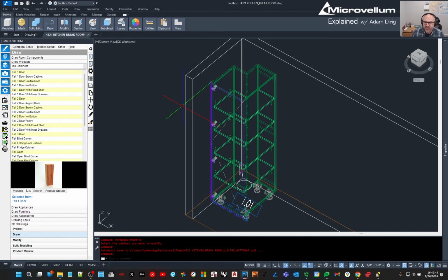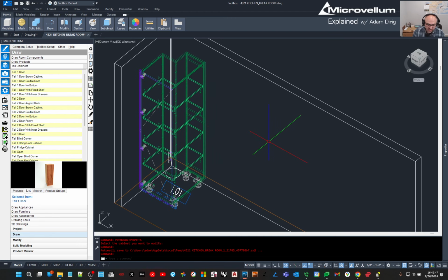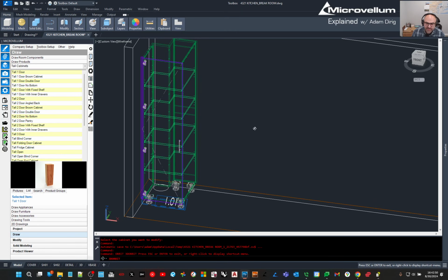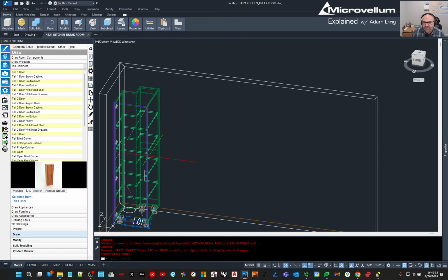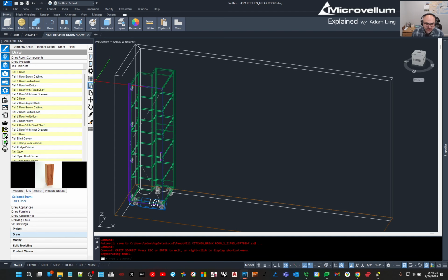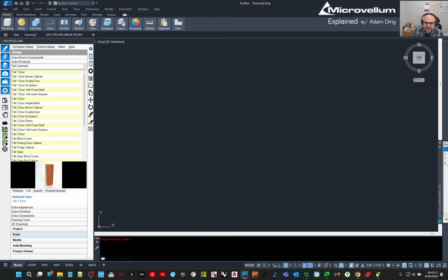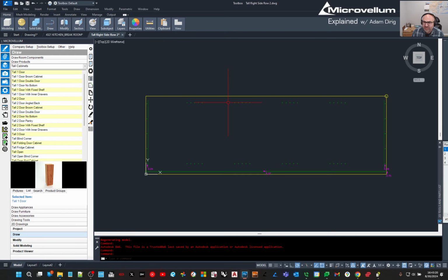But what if you get in a situation where you need to make a change or an alteration to this cabinet that is not necessarily one of those options? Maybe it's a cutout for an electrical component that's going into it, or you have wire chases that need to happen. So we have the ability to take any part or piece in this particular cabinet and drop it down in a two-dimensional view like it would cut on the CNC machine. So I'm going to say, hey, I want to do that. And I want to grab this cabinet side, and it's going to now take that cabinet side and draw it down in a two-dimensional fashion.